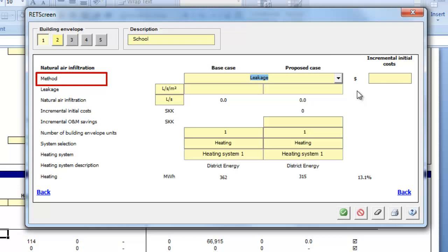Under normal operation, air leaks through the building envelope are driven by wind or stack effect. Thus, the hour-by-hour air leakage changes according to wind speed and temperature. Typical air leakage rates range from 0.05 to 1 liters per second per meter squared of building envelope area for most buildings and climates.